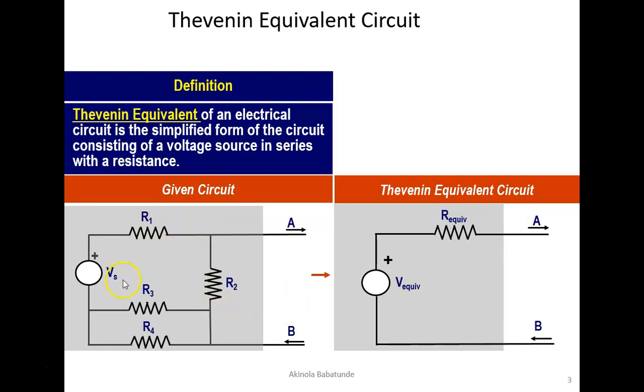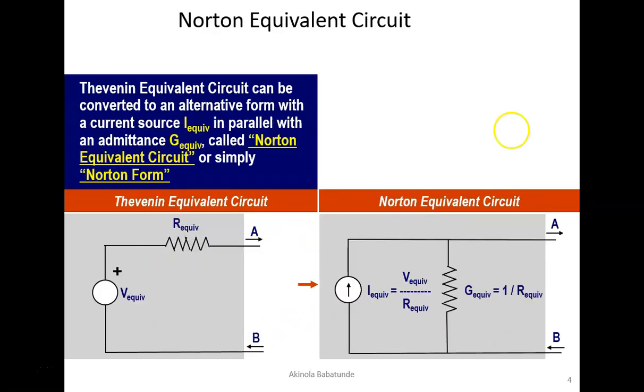So our duty is to transform a complex circuit, whatever the complexities are, to a Thevenin equivalent circuit just like this. So you see, we still retain the terminals here and here. The initial circuit we just looked at has a voltage source and an equivalent resistance in series.